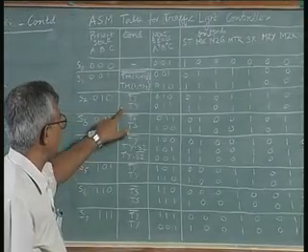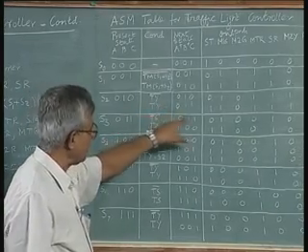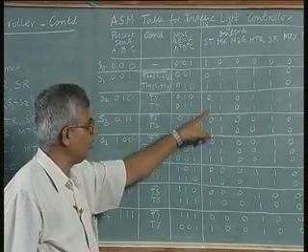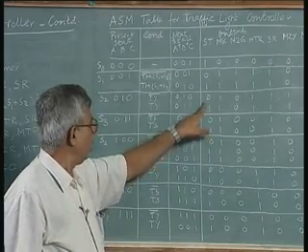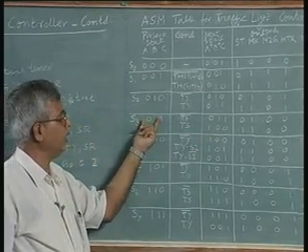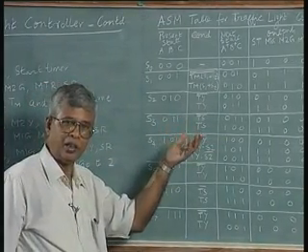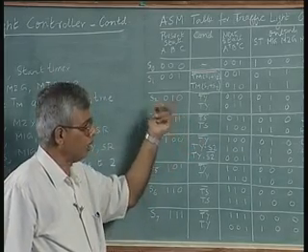When the timer occurs, the time is over, everything is same except that we start the timer. So the same set of outputs with start timer 1, and then it goes to next state 0 1 1, wherein now the yellow has completely turned, it has become now red, and the turn has become green.